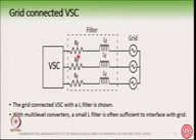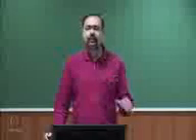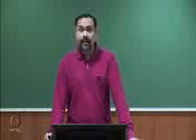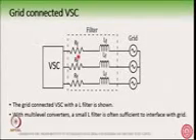For example, the harmonics that flow from the voltage source converter into the grid are attenuated only to a limited extent with an L filter. You can have higher order filters like LC or LCL, but in this course, since we are talking mostly about multi-level converters, we will restrict the analysis to the L filter only.